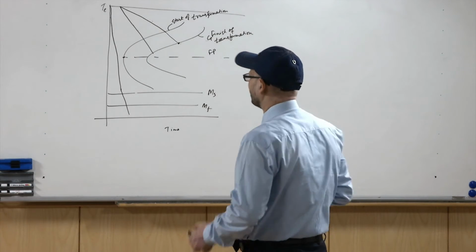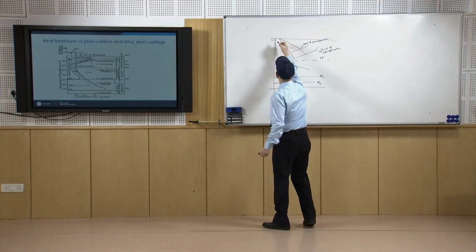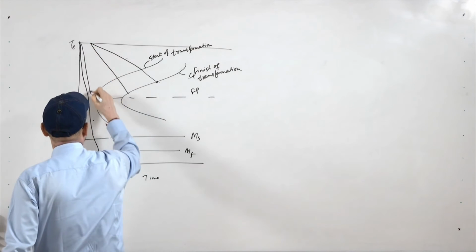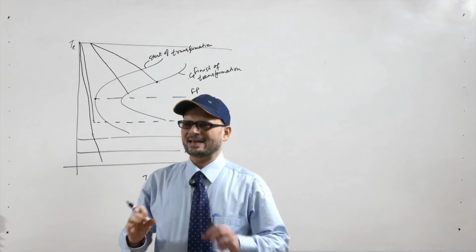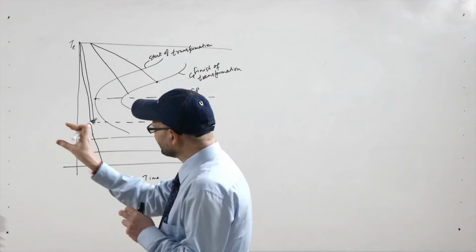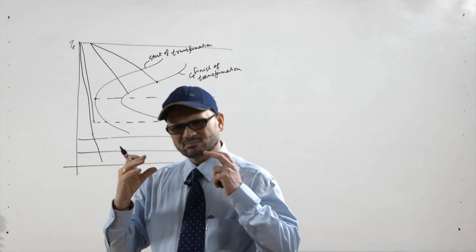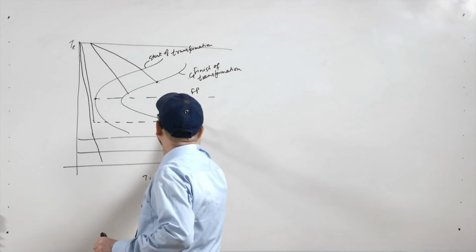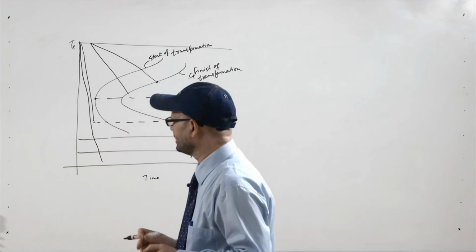Now, what happens for getting such bainitic structures? Normally what we do is we come here, hold it at that temperature and go into this bainitic range. That process is known as the austempering process. Austempering gives you bainitic types of structures.